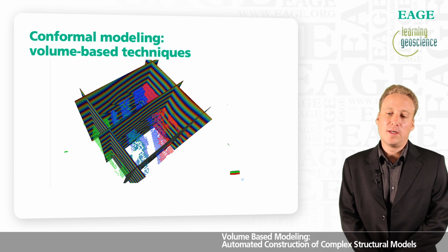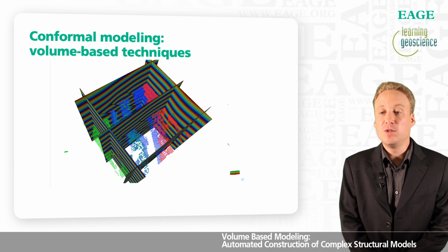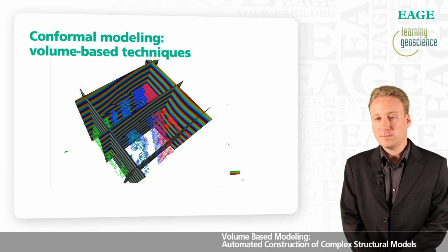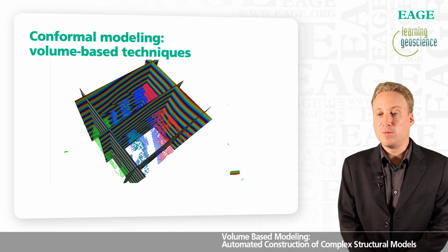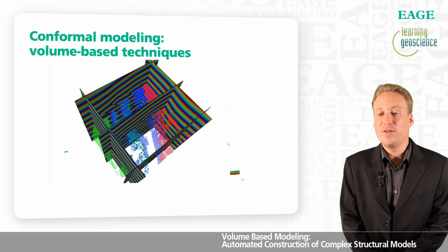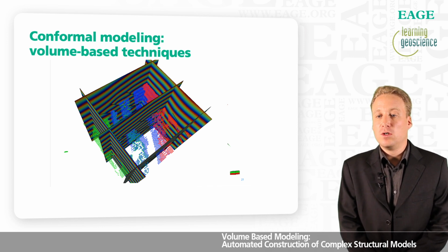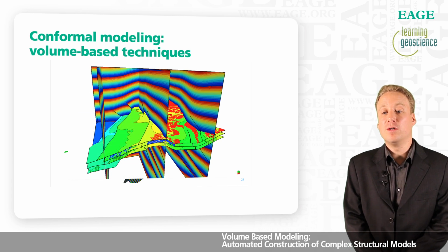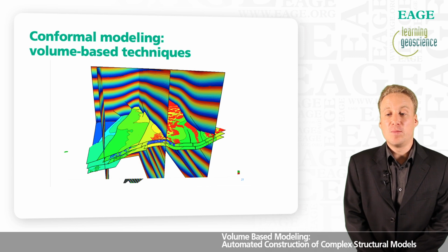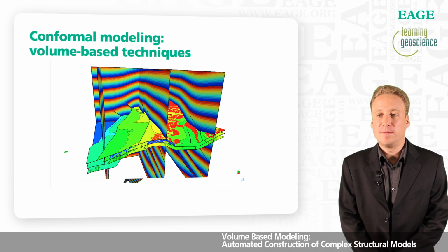Here is a view of the stratigraphy function that has been computed from this model. And as you can see, the stratigraphy function honors all the input data and is properly interrupted by the fault surfaces. So we can build this kind of model without relying on isopach or isochore based technique and without any issue. It's fully automated.